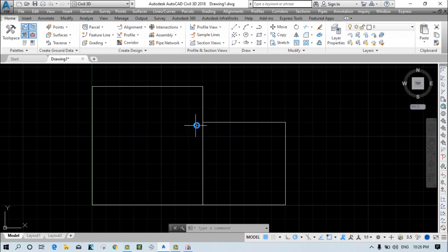So due to this particular condition, that dispersion will not properly allocate. Okay, so that leads to the non-formation of the automatic slab. So you need to add the slab manually. Okay, that's a very big problem in STAAD Pro and ETABS also.